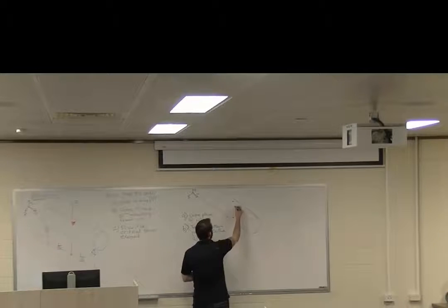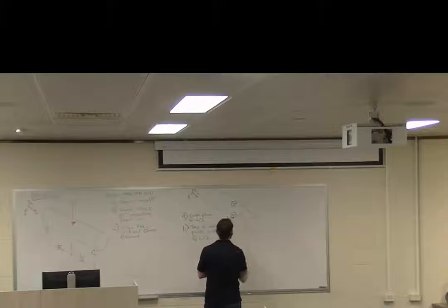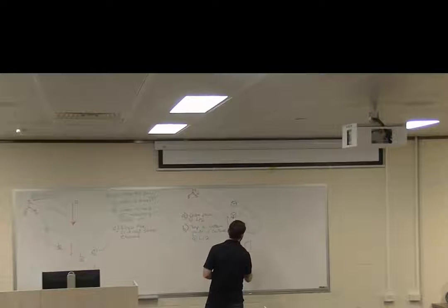And C is draw the critical stress element. So I'm going to draw the top and bottom one. One there, and one there. You draw one in the middle if you want to, but obviously it's 0. And just give myself some space. Remembering I draw the front faces first. With shade. And my back edges.